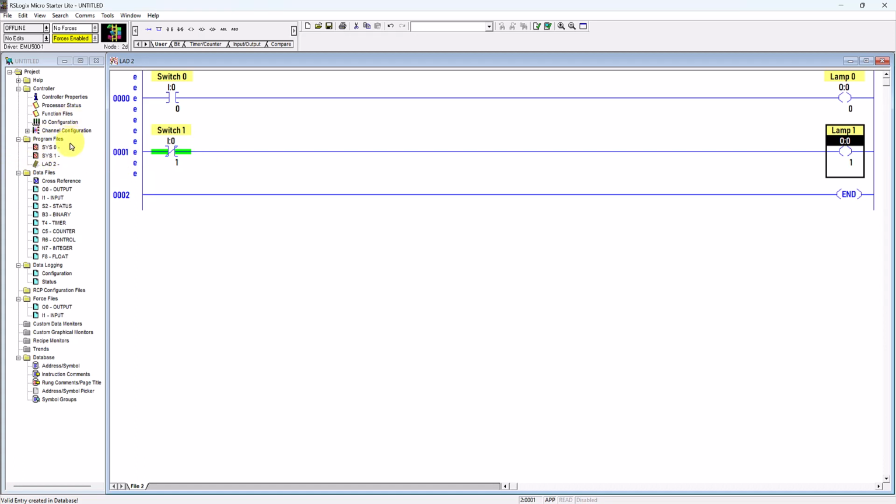Okay, as for the other one, we have switch 1, which for example is normally open. When we press it, the current will flow through the external circuit to the PLC physical digital input terminal point 1. This will energize the digital input 1 internal LED, and this will cause the relevant virtual switch to trigger from normally closed to open. Because of this, the virtual power cannot flow through this rung to energize the virtual output coil.